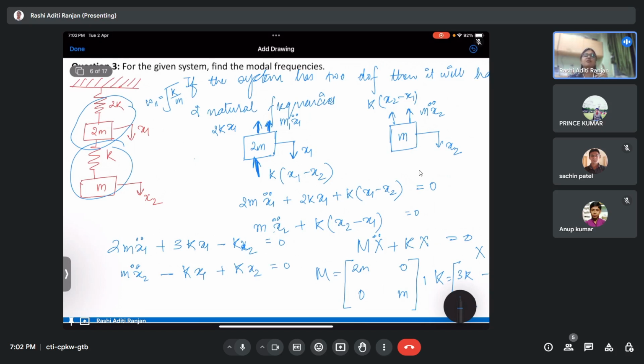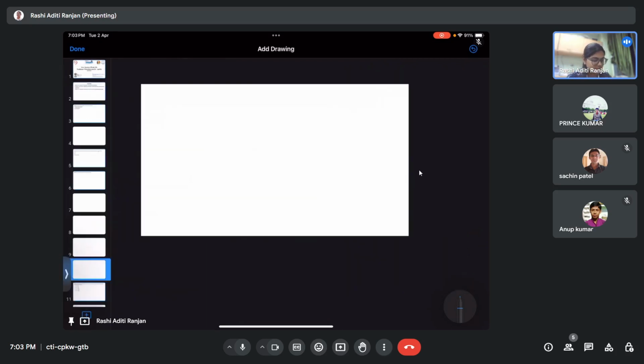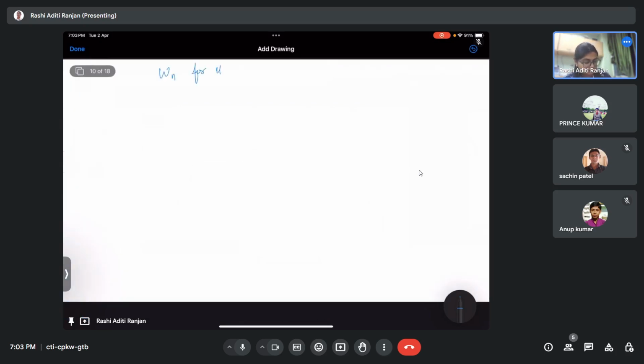If I consider the primary system, my primary system first had a frequency of under root k by m. But after the introduction of the secondary system, if this is my primary system and this is my secondary system, you see that now my natural frequency has changed. And the two new natural frequencies are not equal to the natural frequency of my primary system, isn't it? See, my natural frequency omega n for the primary system was under root of k by m. And the two new natural frequencies after introduction of the secondary system